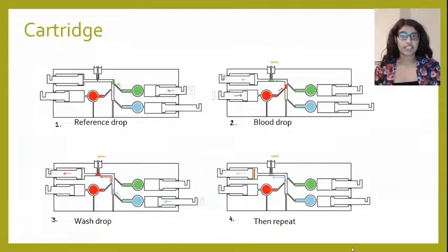Our cartridge contains a custom microfluidic chip designed to move 10 sets of 3 droplets individually to the microcantilever using 4 syringe pumps. A drop of wash is pumped through the channels to wash any leakage and calibrates for a 0 concentration reading. The first drop does this with a known concentration of VPA to calibrate the microcantilever for the reading. The second drop is the patient's actual blood sample to be compared with the reference. The third drop is the wash to clean the cantilever for the next set.